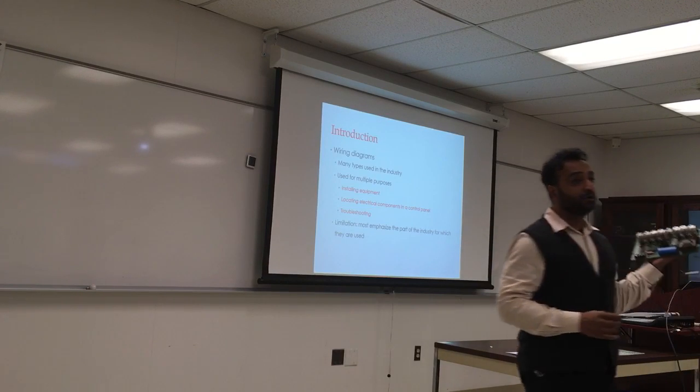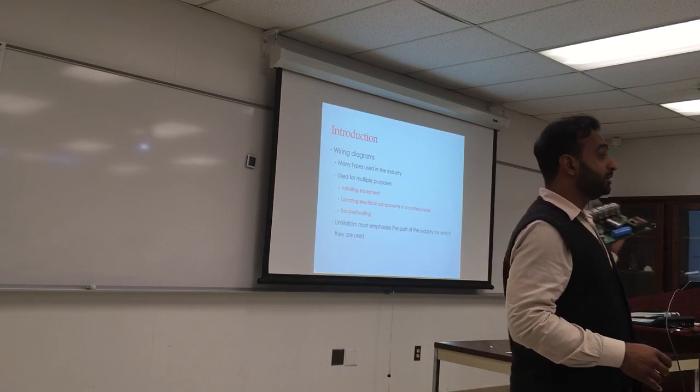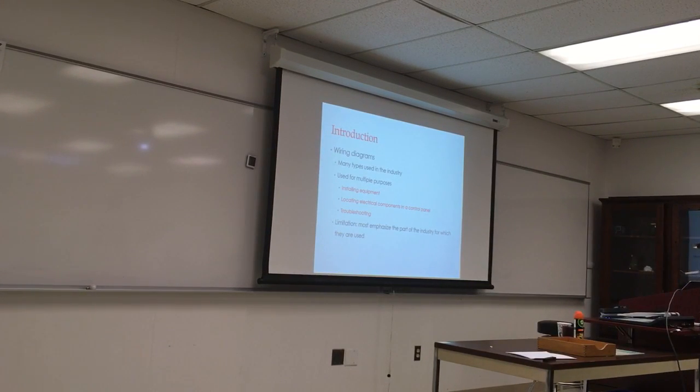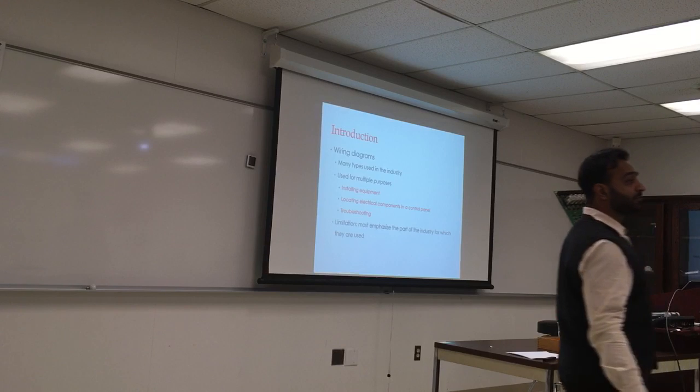What happens if you connect the wrong thing into this terminal? If it's supposed to work on 24 and you put 110, you fry the board. And it happens a lot, more than you think. If this terminal, for example, is designed to run on 24 and you put 120 here, the board will be fried. And these boards are not fixable. See, it's all printed in. So you're probably gonna fry the board, you have to change the entire board. These boards range from like $200 to $500.